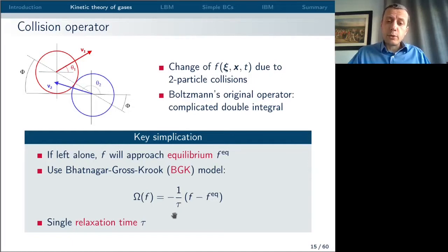That is really important to know. Of course, you can come up with a simple model, but it may be oversimplified. But the BGK model, despite its heavy simplicity, is still enough to recover Navier-Stokes behavior, and that is everything we need in order to solve the Navier-Stokes equation. Because we will not use Lattice Boltzmann to solve the Boltzmann equation, we will use Lattice Boltzmann to solve the Navier-Stokes equation.